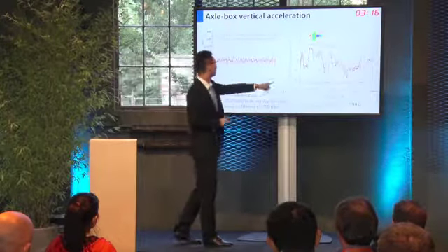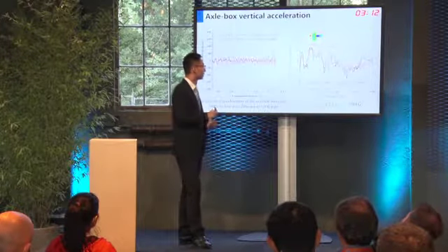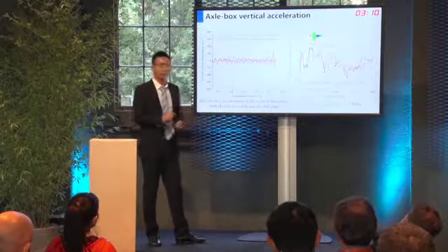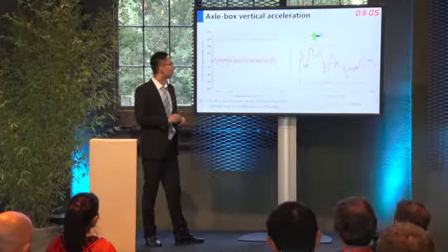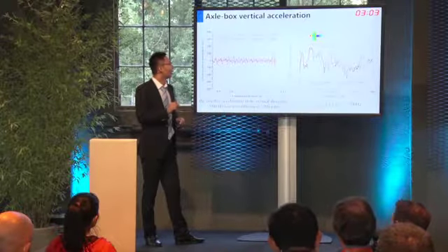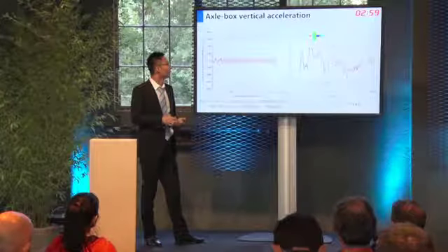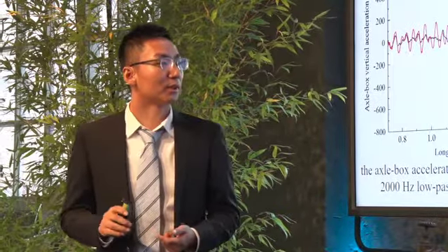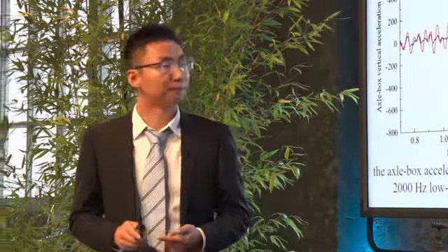So this leads to this figure, where the acceleration of the resilient wheel is larger for the wavelength of 80 millimeters. But generally speaking, we can say that the resilient wheel can decrease the acceleration above the vibration isolation frequency.